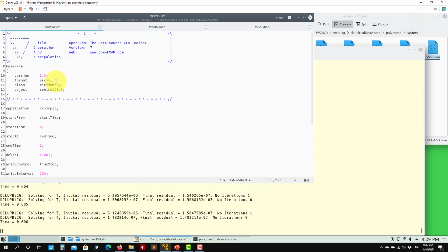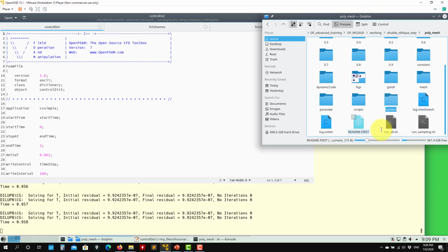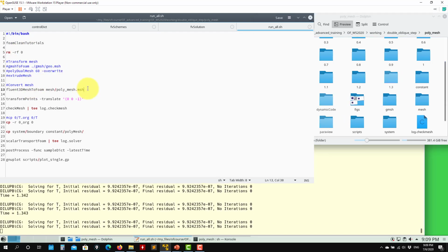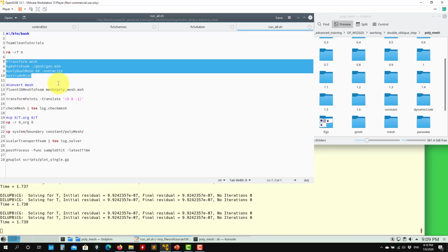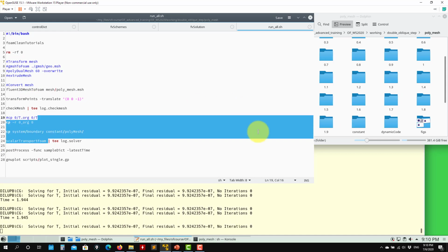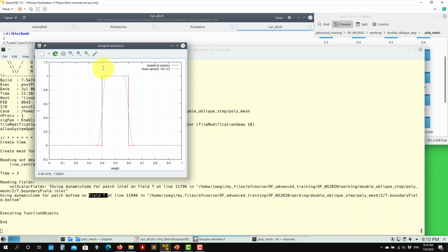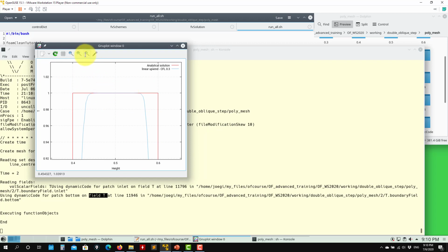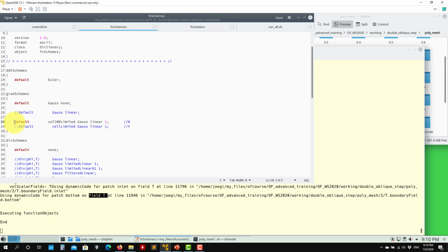Okay, in this case again I left the time step a little bit low, so you can increase it. And just a reminder also, remember that you have this grid and you have all the steps here. So here you can see that, well, I already converted the mesh to this format, but here also you have all the steps to get the mesh from Gmsh. Okay, and we're using this specific solver. Okay, so see that the polyhedron mesh actually got a good solution by using this limiter that in the triangular mesh was a little bit oscillatory.